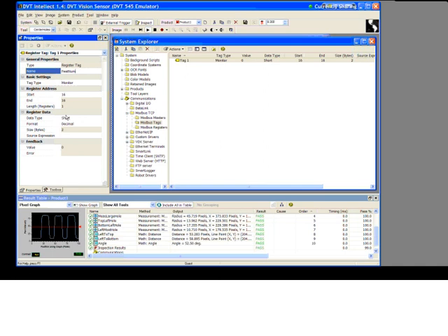And this is something that we need to make sure that we are aware of, and that is the different data types and their size or the number of bytes they occupy. Because the terminology is a little bit different between Intellect, the data types for that tag, and the OPC configurator tool and the data types for each item that we add there.